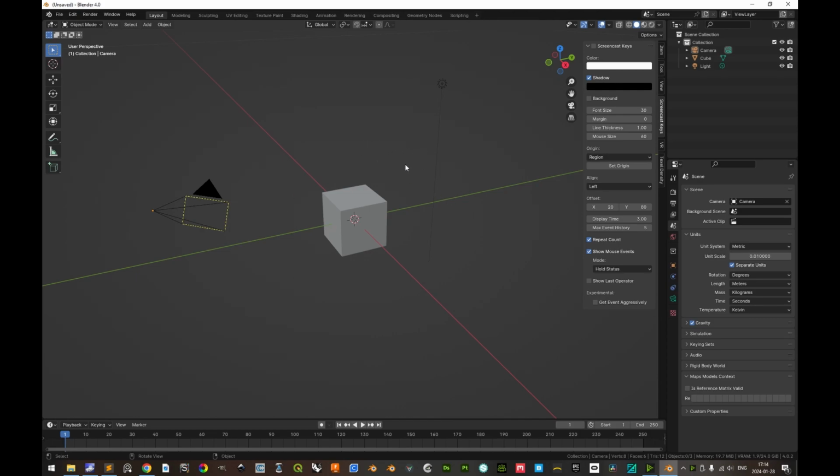And then the first thing that we're going to do is to select everything. I'm going to activate this plugin here so that you can see what keys I am typing. So select everything with A and then press X to delete and confirm with left mouse button clicking. It is very important for the succeeding scripting that you import the model into a completely empty scene.